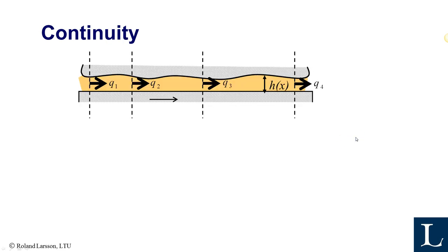Okay. Next step in the derivation of Reynolds equation is to assume or discuss continuity. Apart from the force equilibrium, continuity is the second law we must always obey. And if it's an infinitely wide bearing, there is no flow into the screen here. It's just along the x direction. And since there are also stationary conditions, steady state, it means that there are no time effects.